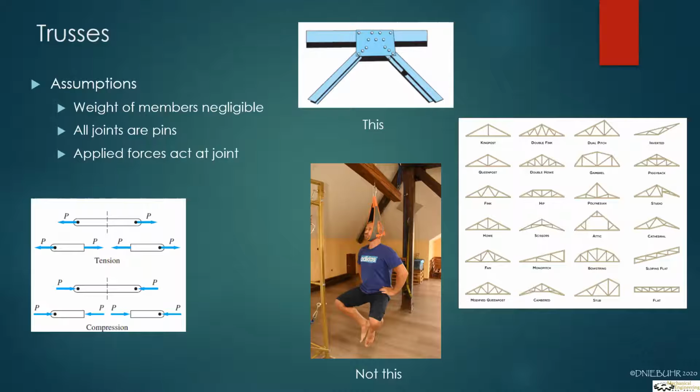And so the arrows would then point away from the pencil on both ends instead of towards. So that's the difference between the two. And the thing is, you don't have to know ahead of time when you're doing your calculation whether it's in tension or compression. You just have to do the calculation, and if you're right or wrong, it'll tell you by a negative sign.